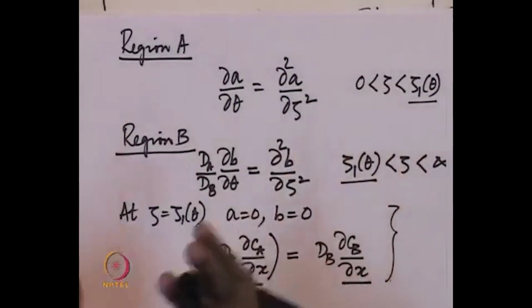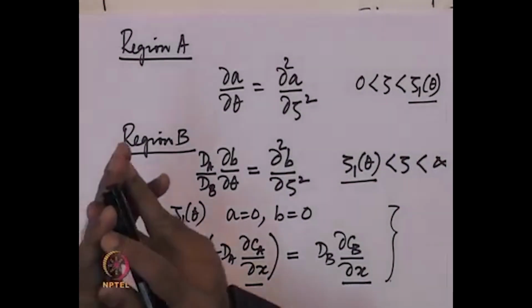The instantaneous reaction regime is one in which A diffuses from the interface and B diffuses from the bulk, and they meet and consume each other at a reaction plane, which is located somewhere within the surface element. This reaction plane itself starts at the gas liquid interface at the instant the liquid element arrives at the interface, and as the element ages at the interface, as it spends more and more time at the interface, the reaction plane progressively moves inward into the liquid element.